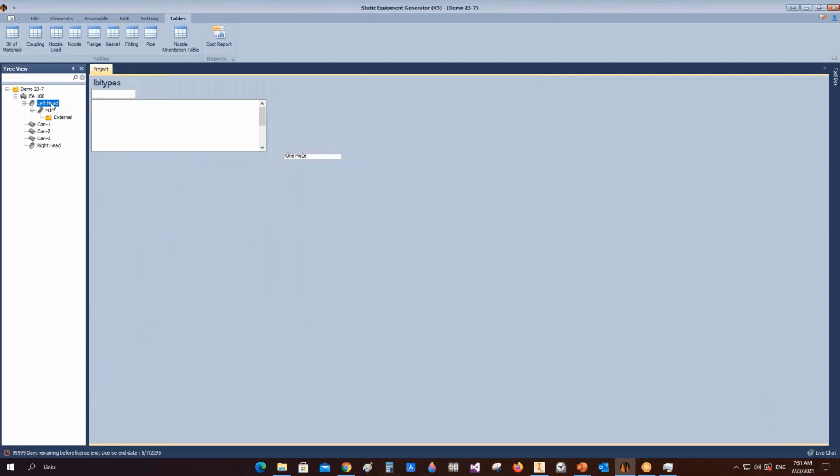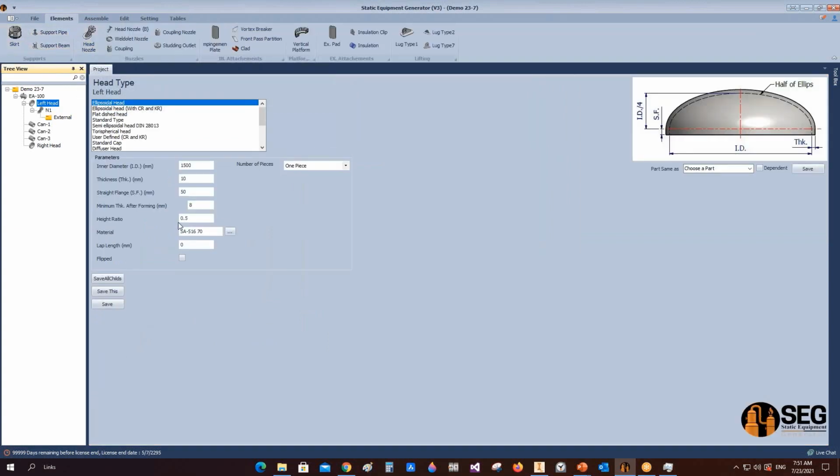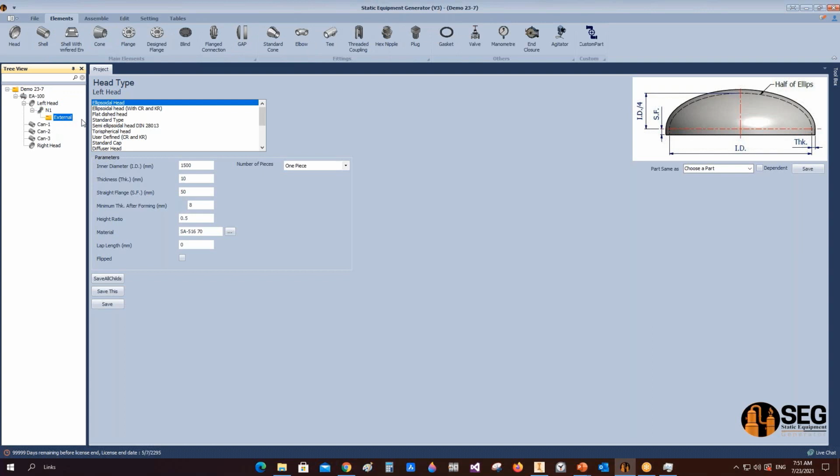Now let's add another nozzle, but this one we will add a nozzle with external and internal projection. So let's add a nozzle head type B. This type includes internal and external projection. As you can figure in N1, you have only an external connection point.